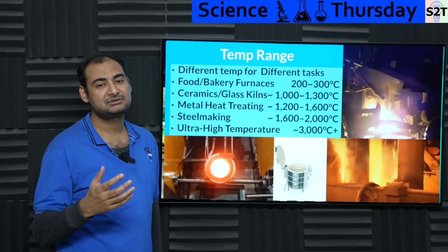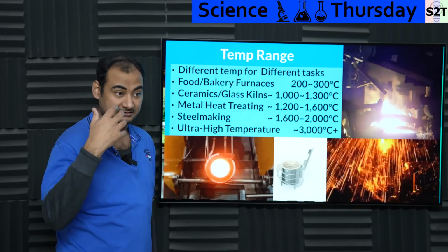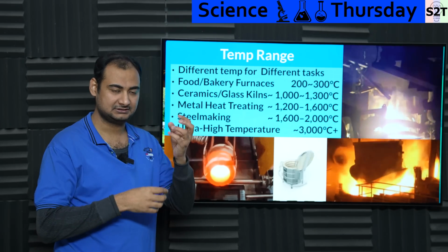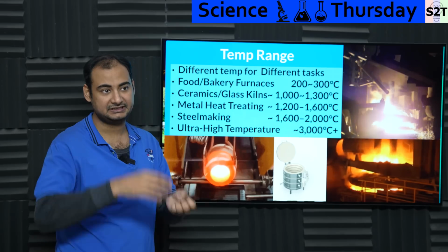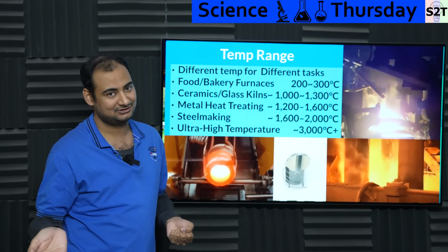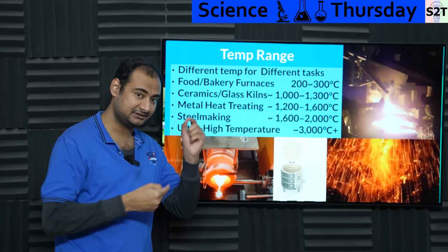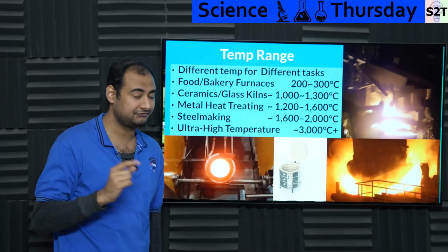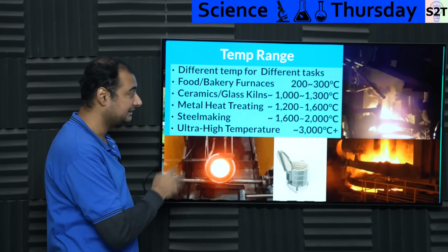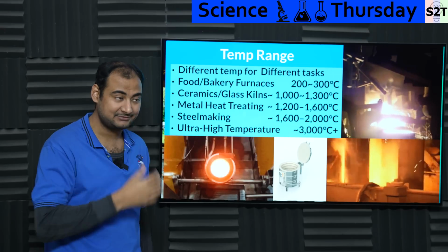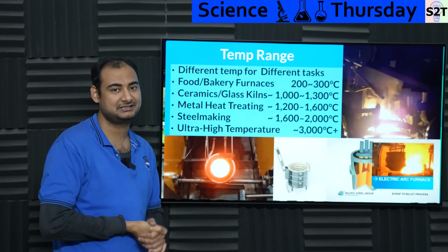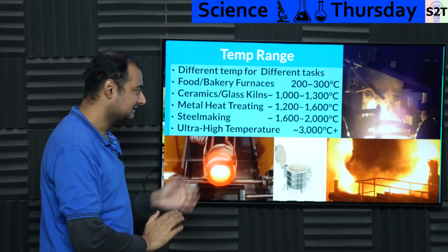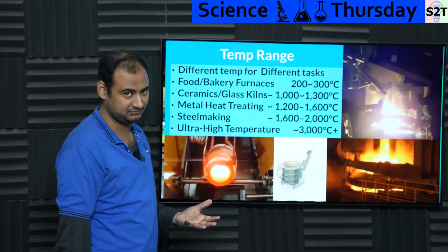And many times you will ask, okay, if steel melts at this temperature, why does the furnace have to be so hot? It's energy flow. If you do not have a high enough delta between your source, as in whatever is creating that heat, and whatever you want to melt, it will take too long. It will be too wasteful. That's why your soldering iron, even though solder itself can easily melt at 250 degrees Celsius, can easily go 300 or even 450 degrees Celsius. That's by design. Same way with a furnace: even though it does not need to be that high, it will take forever to reach equilibrium at that temperature. But if you have a high flow rate, as in the T delta is huge, whew. So that's why the temperatures are generally much higher than the bare minimum.